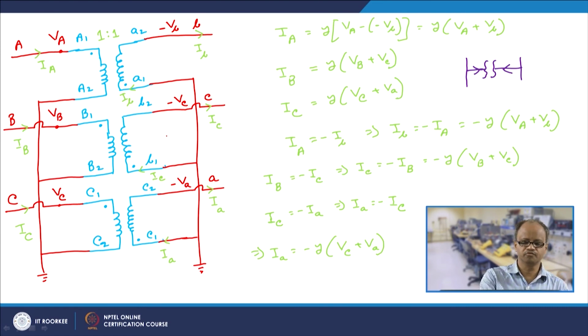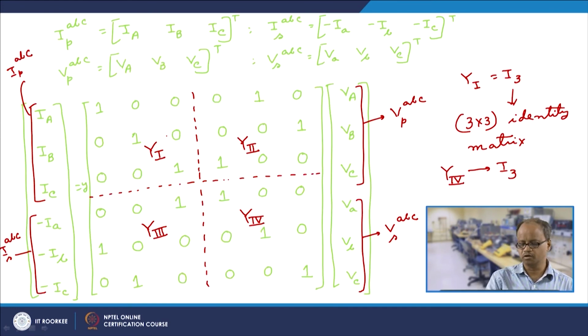Once we had denoted all these voltages and currents properly, taking into account the standard dot convention, we simply wrote down the equations, and from there found the transformer admittance matrix. So, to model a transformer, nothing is to be remembered; it can be done in a very easy step by step manner.